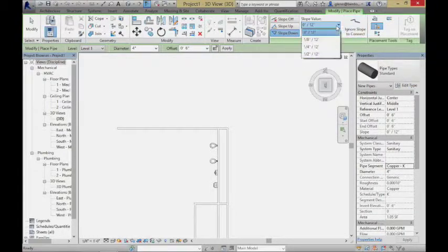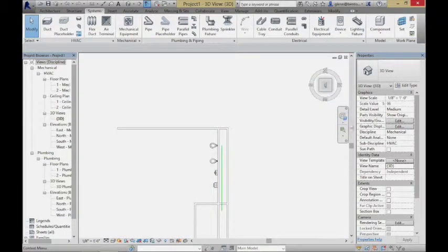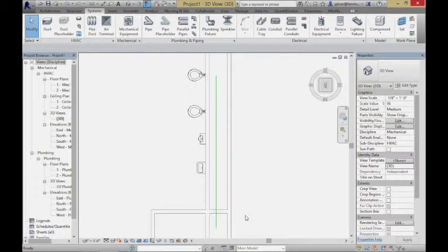We have a slope value here. We have all sorts of stuff. And does anyone know what the amount of slope you have to put in for a sanitary pipe is? Minimum 1/4 inch. Okay, let's put that in. Thank you. I'm going to run my little sewer pipe here. Just bring it on down. And that was ever so unexciting, but it sort of works.